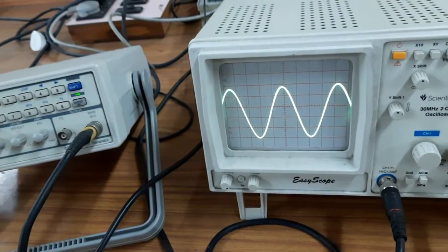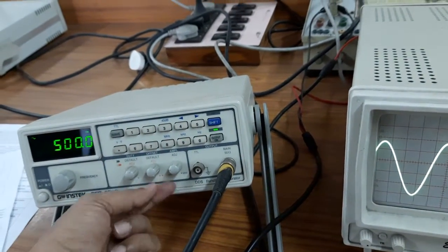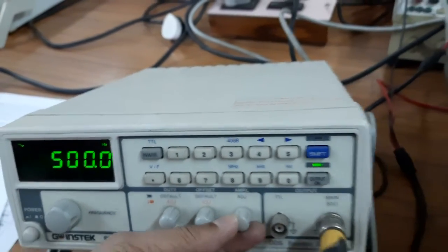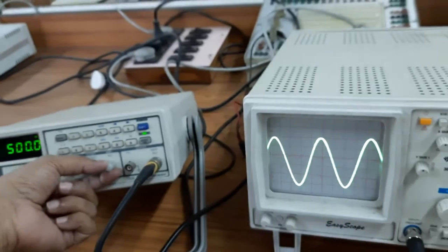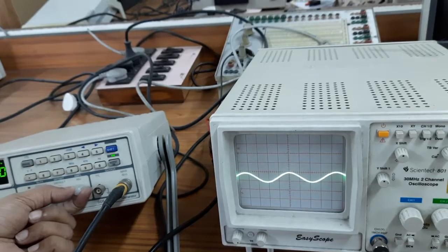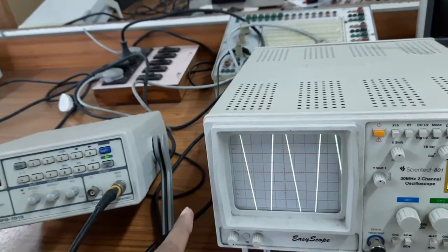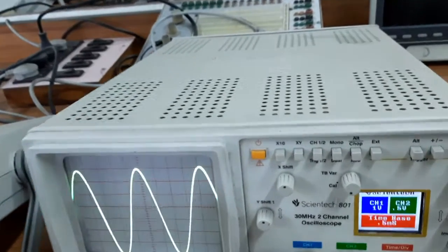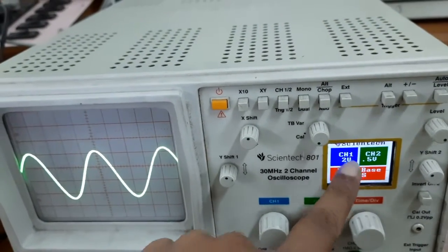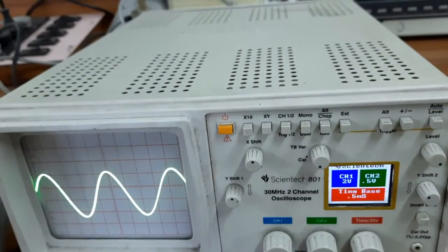Now if our voltage changes, how do we change the voltage? In the function generator, one knob is there, that is called amplitude. By changing this amplitude, we can change our voltage. Just follow. Now it is very high amplitude. Now it is very low amplitude. So we can set our amplitude from here. And if it is very high, then how to measure this? We have to change our scale. We can change our scale to 1 volt per division, or we can even change it to 2 volt per division. Then what about the reading now? That will be multiplied by 2 volt. Then we will get the exact reading.